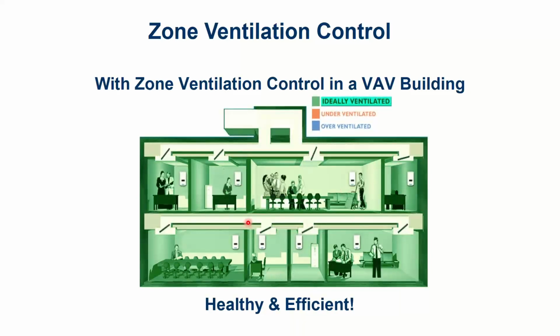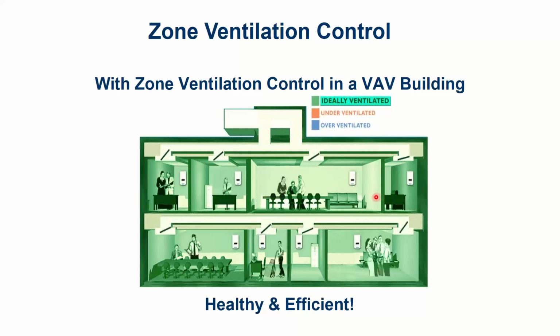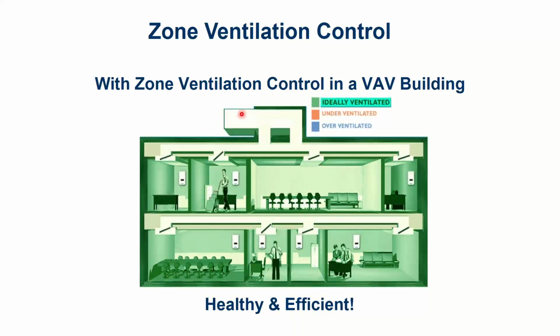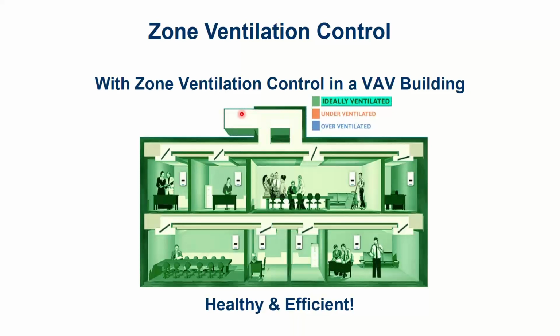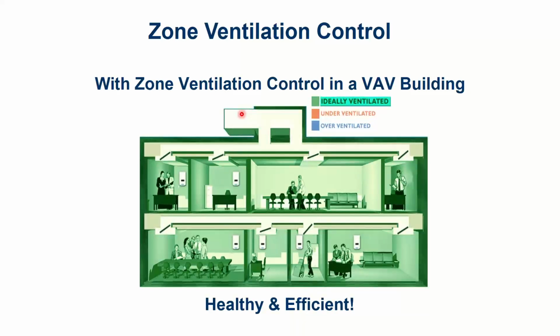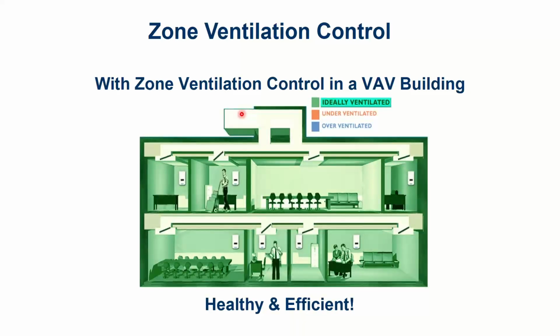And then I add a CO2 sensor on the wall, and when fewer people show up, I can throttle the damper back some. The same thing works on single zone. When you have one CO2 sensor controlling the main outside damper, don't think of it as making the damper go more open. It doesn't do that. Think of it as starting at the code required CFM, and it actually goes below that when fewer people show up. The mechanical and energy codes allow me to do that.